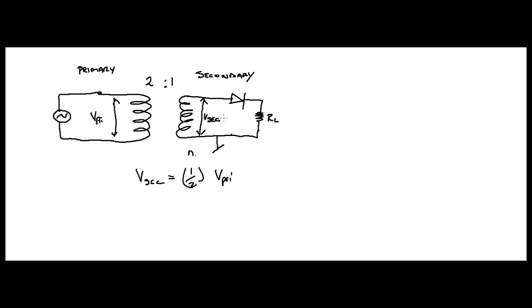So when you know what that is, and depending if you have RMS or peak, suppose it's peak, you can simply check the peak voltage going across RL. That's simply going to be V secondary, or VP secondary for peak, minus 0.7 volts, right? And then you know the voltage that is going to be dropped across this load resistor.